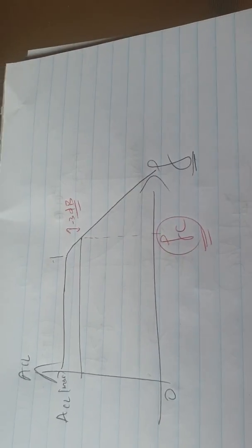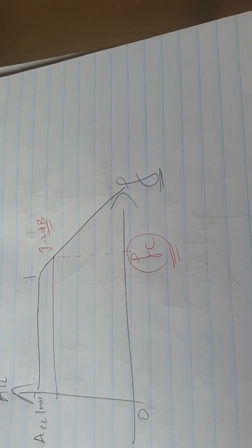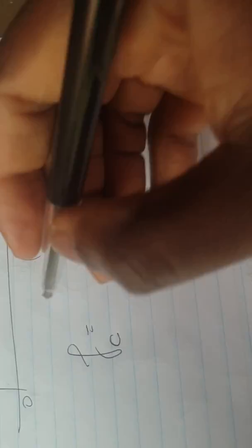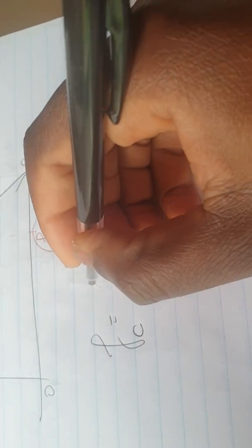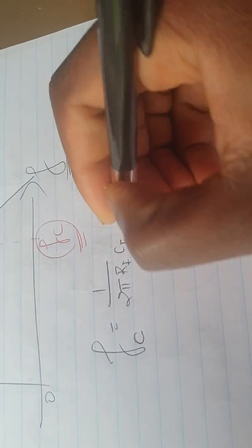So now how do we get to choose that cutoff frequency, FC? In terms, how do we get to choose a certain value of C and a certain value of R to design for a certain cutoff frequency? When it comes to the low pass filter configured the way it is drawn in the circuit shown here, where we started, the cutoff frequency we obtain, which is the frequency 3 decibel below the maximum gain, will be equal to 1 over 2 pi RF CF.